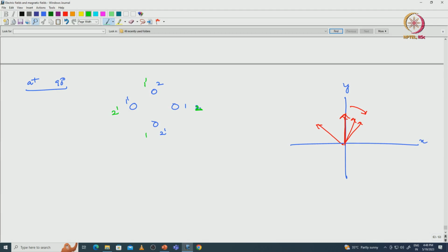Now coil 2 we are exciting. The 2 dash conductors are there like this, and the second conductor has positive current at 90 degrees, here dot, here cross and here dot. So the magnetic fields will be, again apply the thumb rule. With respect to the cross we will see the clockwise direction, with respect to the dot anti-clockwise direction. Anti-clockwise direction means in this manner. So the resultant flux is in this direction.